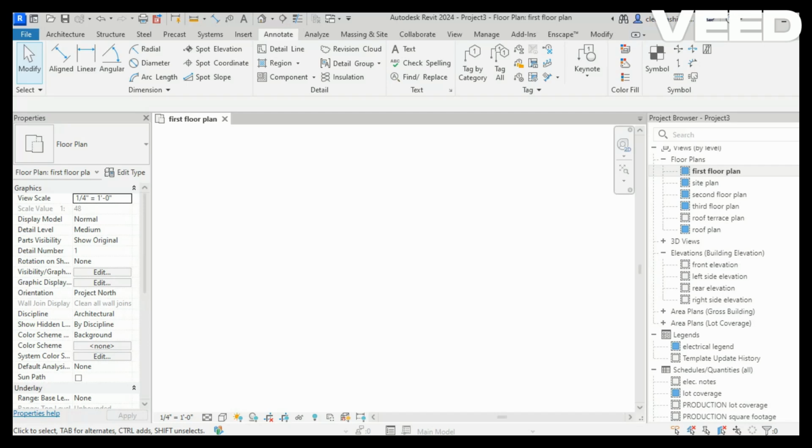We're going to go over the view cube, okay? We're going to show you guys how to manipulate the scale of a project. And we're going to show you how to turn off and on the project browser, which is over here, and the properties menu. We'll get more into that as we matriculate. We'll show you how to look at the 3D view once we draw the walls, okay? And we're going to show you how to put in elevation markers and how to toggle the graphic display options, right?